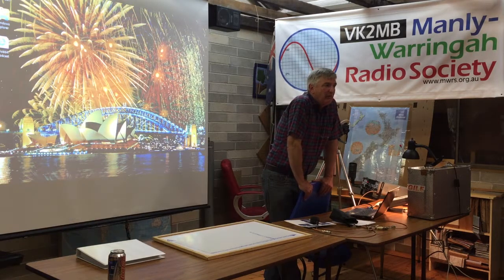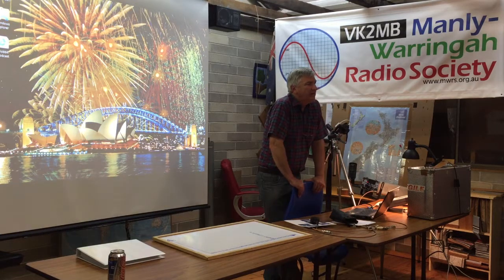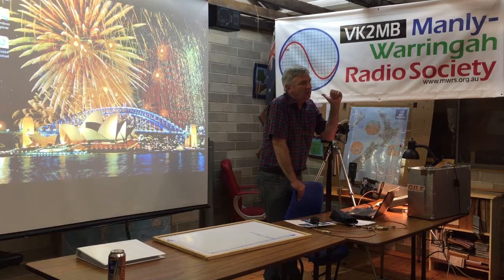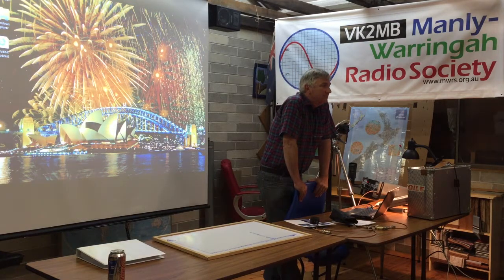Where is that device that's making the decision? Because if you're talking about over more than 100 kilometres, you can't just have it at one end, because there might be signals at the other end. It's changing 10,000 times a second. It's very, very fast spread spectrum, but it's actually analysing the band and applying noise blanking to any individual spot frequency which is noisy in the band.